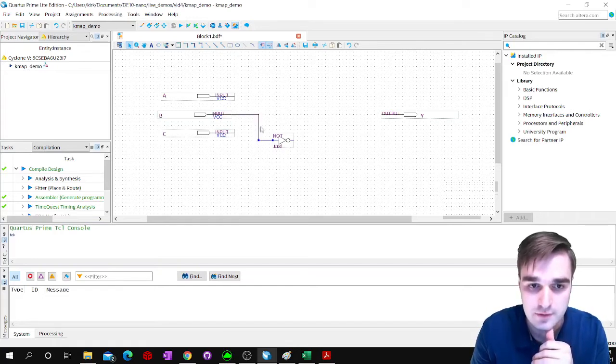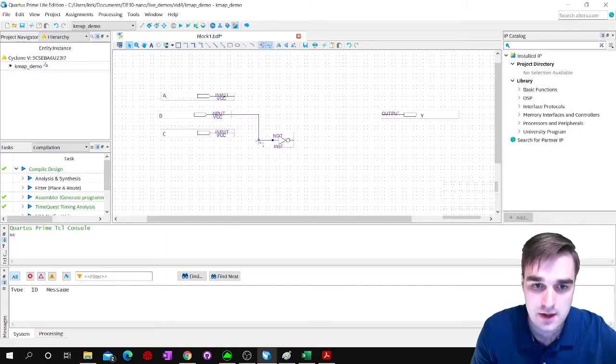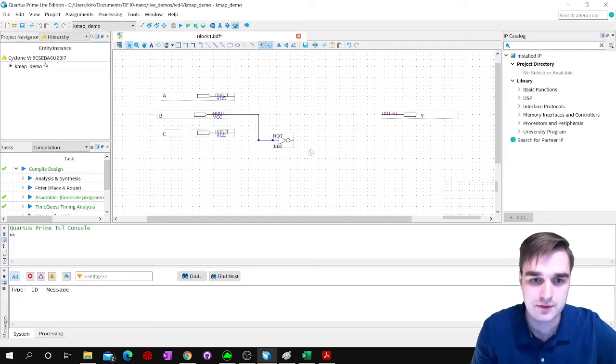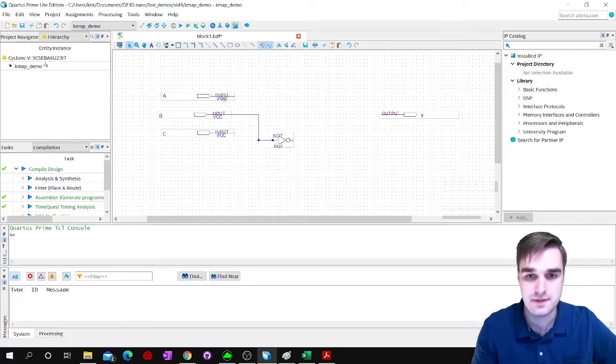You only get 1 turn per mouse drag. So I let go right here, and then I click the little tip right here until my crosshair changes, and I click and drag it out here, and it drags out a wire and it connects it. So now I have a connection to the NOT gate. And then additionally, we need the OR. We'll come back to the OR gate. Okay, so let's do the 3-input AND.